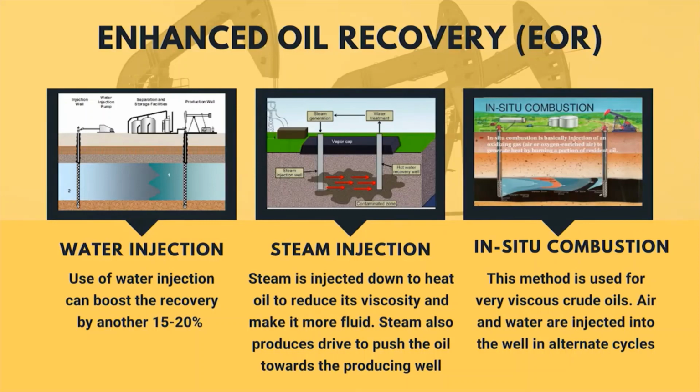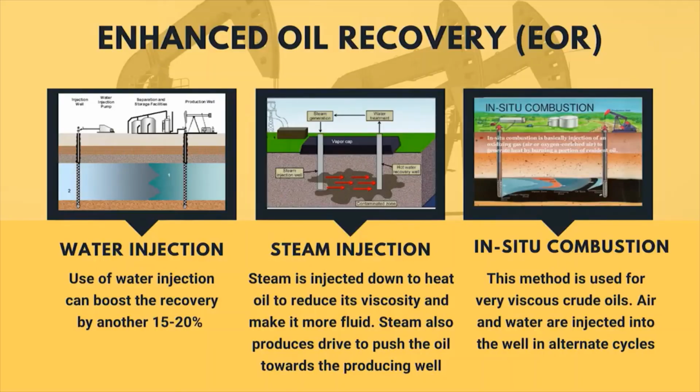The second technique is steam injection. Instead of water, we are now allowing high pressure steam. This is employed where you come across highly viscous oil. This highly viscous oil is diluted by admitting the steam. The steam is melting the oil and the viscosity of the crude oil is reduced, and that helps the pumpability from the bottom of the earth to the upper surface. The third technique is in situ combustion.